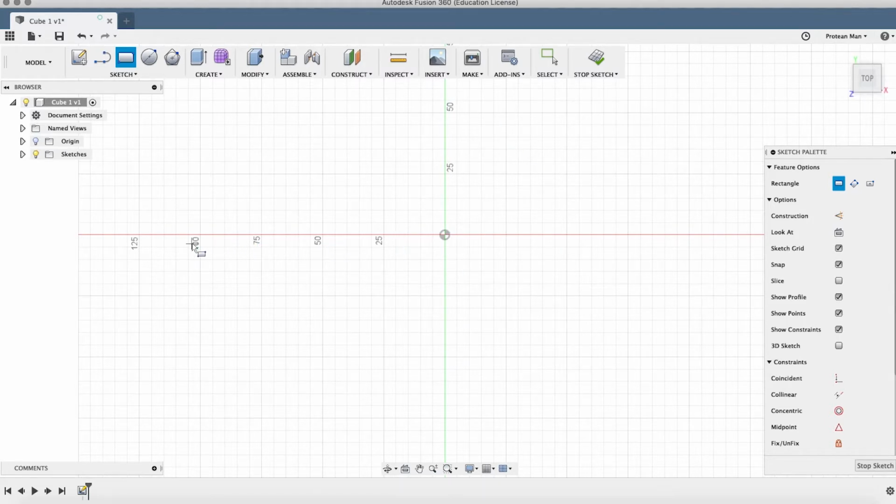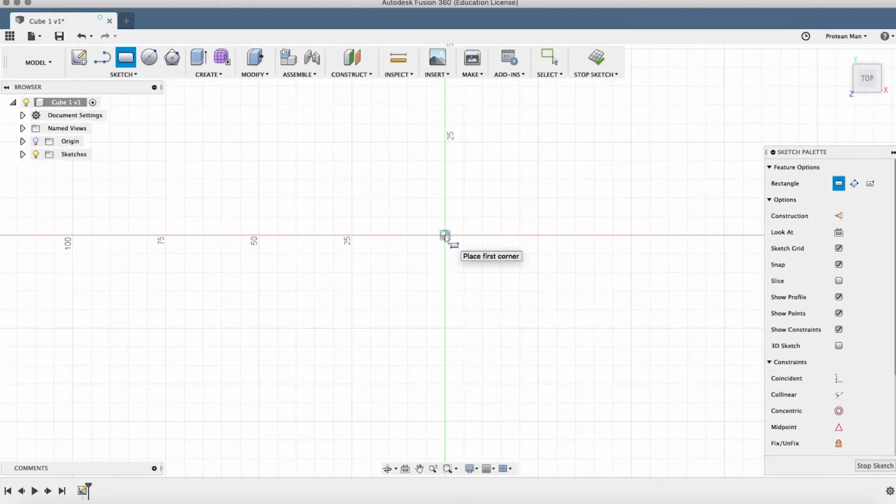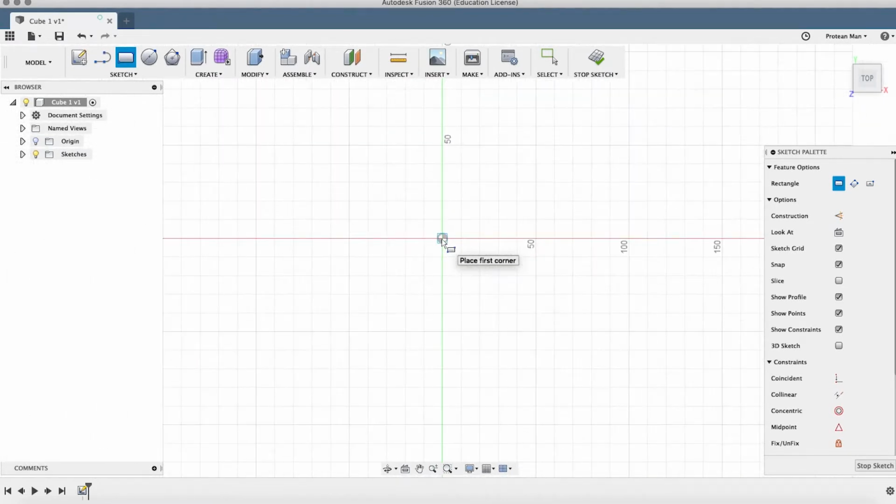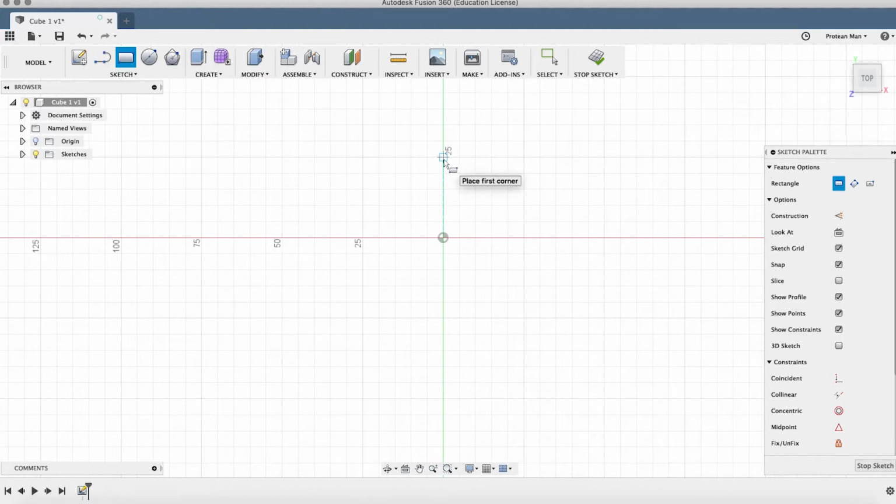So here we go. I want you to go up. If you look at the very center, there's this crosshairs, this 2-part crosshair. That's the very center of the canvas. We have the angles, the planes. We have the X and the Y. It's also here. X is red, Y is green. And these numbers are millimeters. So every box is going to be 5 millimeters. We can zoom in with our mouse wheel, and we can see even smaller boxes as single millimeters. You can zoom even further into 0.1 millimeters, but we're going to stick with just 5s for now. So it should be default as set.